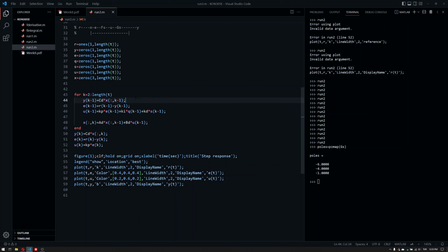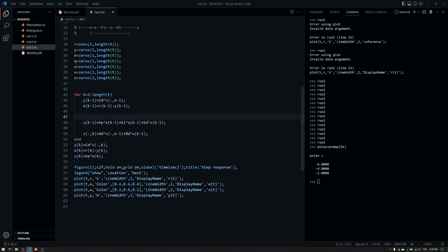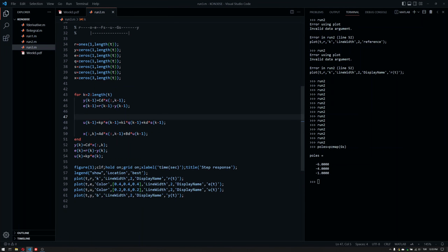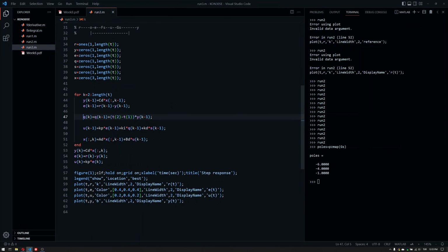At this exact point, we need to calculate two more signals so that we can take the linear combination here. And we know from F integral that this is going to be the case here. So I'm just directly taking it here. So qk minus 1, I know what the sampling time is, tau, but I'm not taking the integral of the output or any other vector, I'm taking the integral of the E signal here, the error. So that's that. That's also nice.